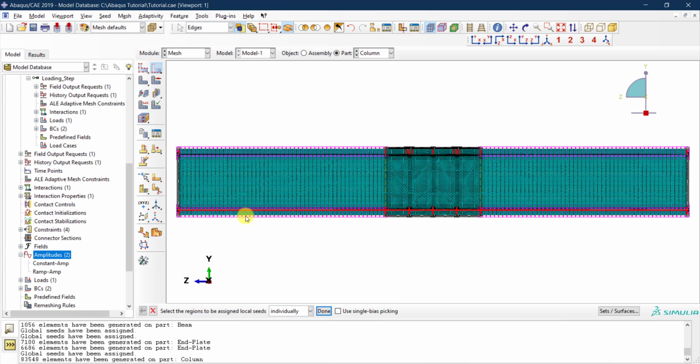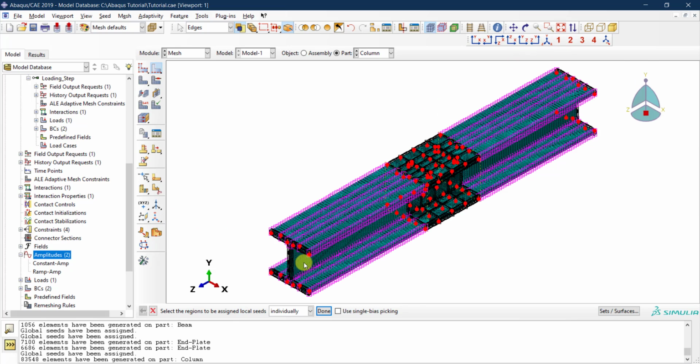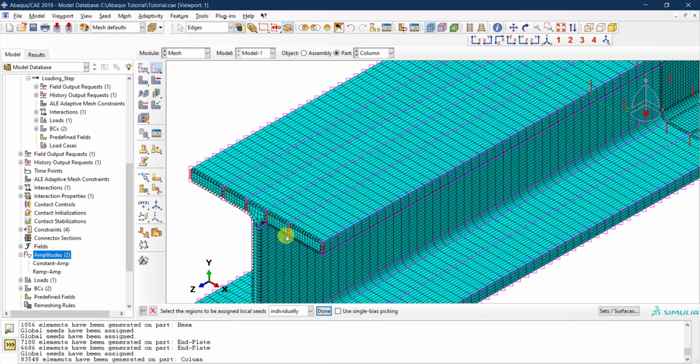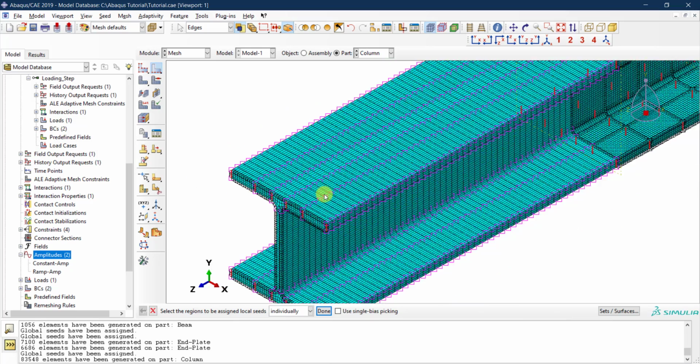Oops, I selected another one wrong. That's fine. I can click control and reselect, so to unselect, then shift, and then I select again. Let me do it here, very small box, so I'm not selecting anything outside. That's it. So right now I select all the interior edges, the vertical edges pretty much.